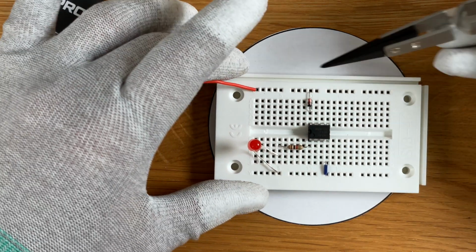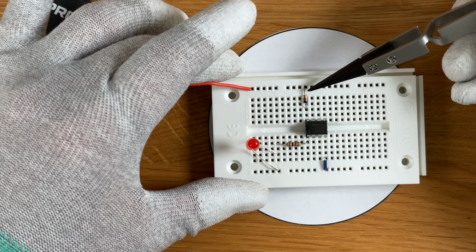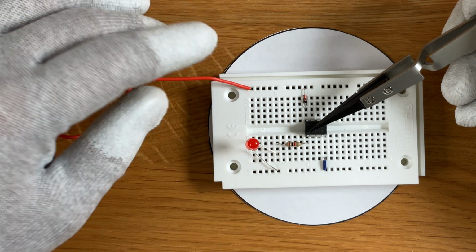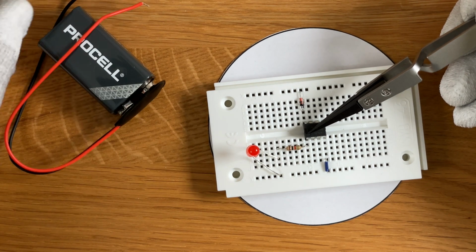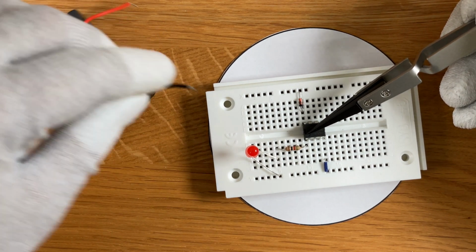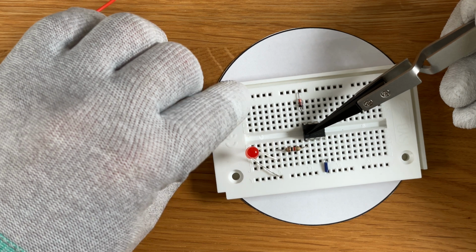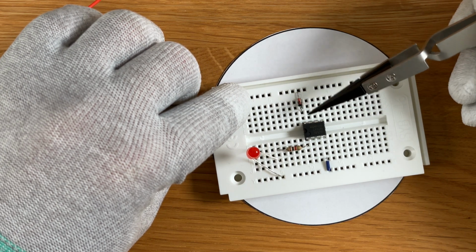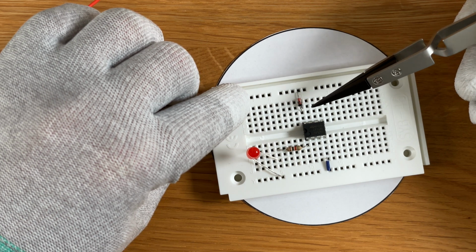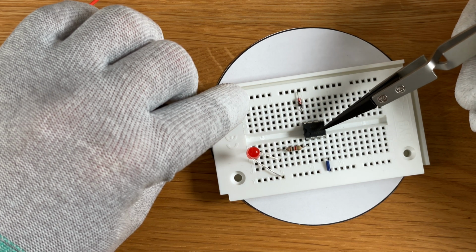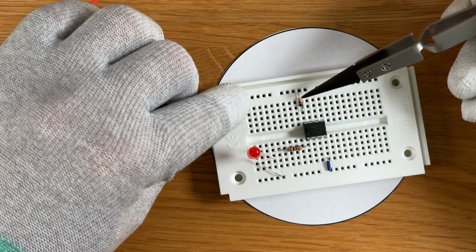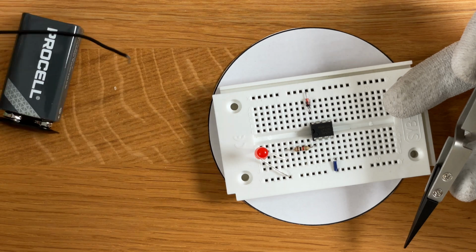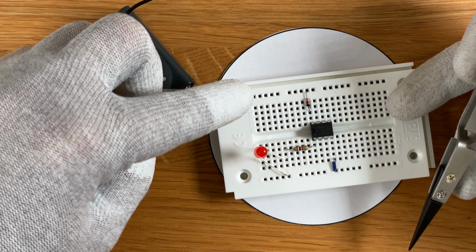And once current flows, this ensures that the current only flows in a single direction into the operational amplifier, because if I confuse myself, for example, if I should not think properly and by accident connect the negative power connector to this power rail here, then this diode here, it's not an LED, it's a diode, will save the life of the operational amplifier by not letting the current through in the wrong direction. So this is the purpose of this diode here. It's for safeguarding the operational amplifier.